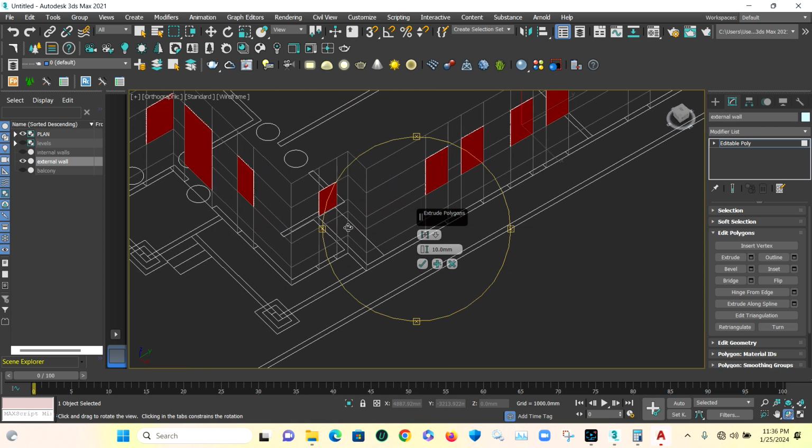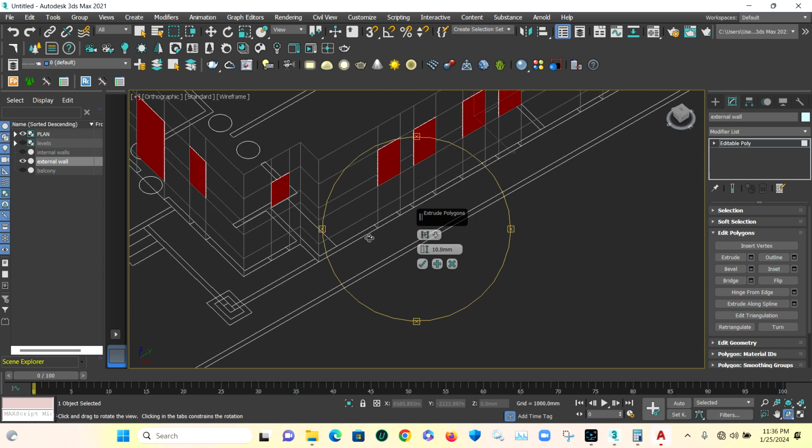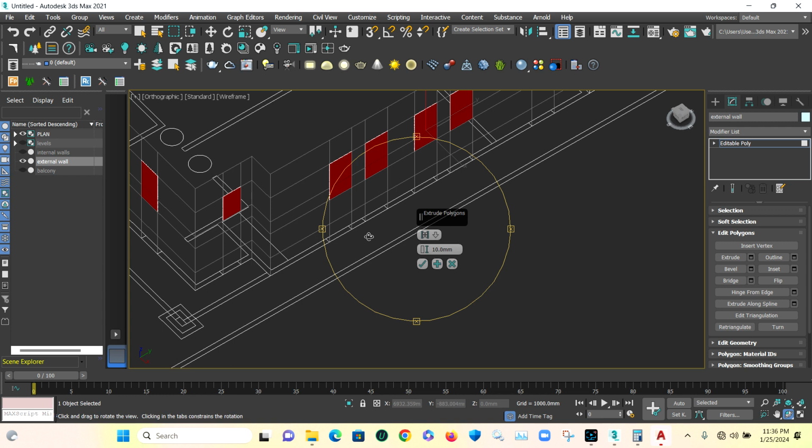Now remember, here we used 150 blocks, and as such our window is supposed to be just 150. Extrude inside 150. You're getting me? Now remember, in real life, for instance, if you're laying the blocks, when you get to that point, you stop laying until you get to lintel. Now this extrude represents the top of that block. There is still 150 blocks. Assuming you have 9 inches blocks, 225. Now you use that, but say we're using 150 blocks. So what do I do now?